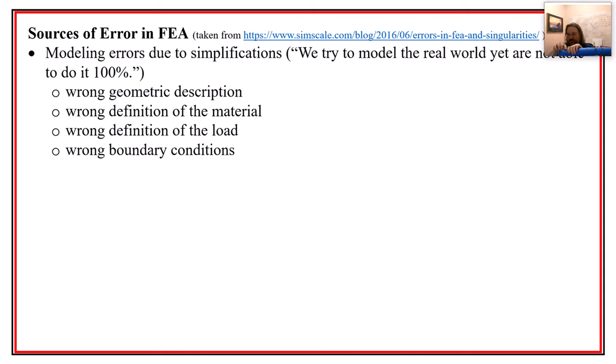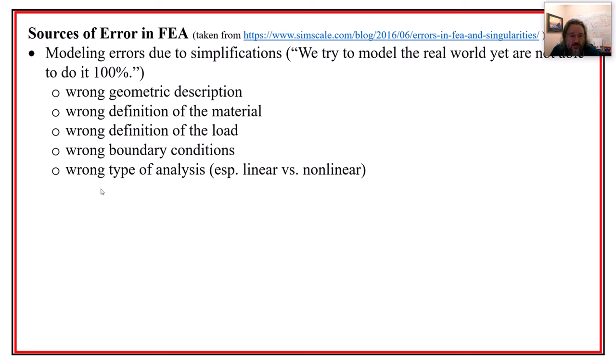Because if you just maybe cut off, make a little section right here, and we'll do something we'll call split lines, and you just tell it to hold all the nodes right there, it's no longer simply supported. It's going to be fixed because it's going to grab each of these nodes and it's not going to allow them to displace. And so now, while you thought that you were going to get a simply supported reaction right here, you're actually going to get a fixed one.